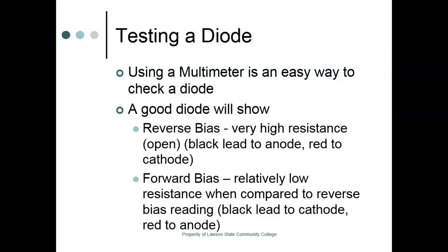So what we're doing is, when I've got it on ohms, we're using what we call a constant current source, which means your meter raises the voltage until a certain current flows through the circuit. And it's usually around 10 milliamps. It's not much at all. We can measure this. We can put a meter on ohms, and then take another meter, put it on ammeter, and measure it. Okay. So what it does now is it calculates this voltage right here, and it's milliamps. So the milliamps and the volts are going to be together, right? You understand what I'm saying?